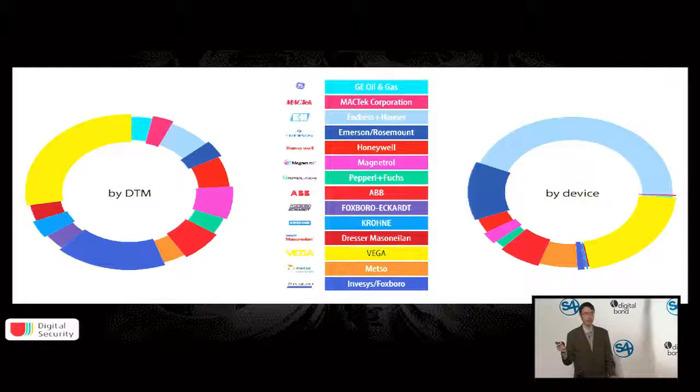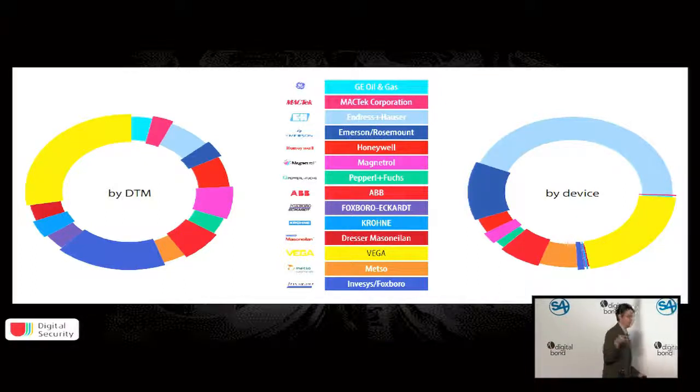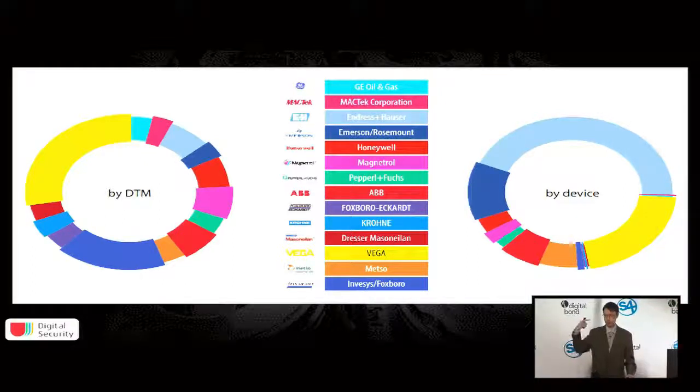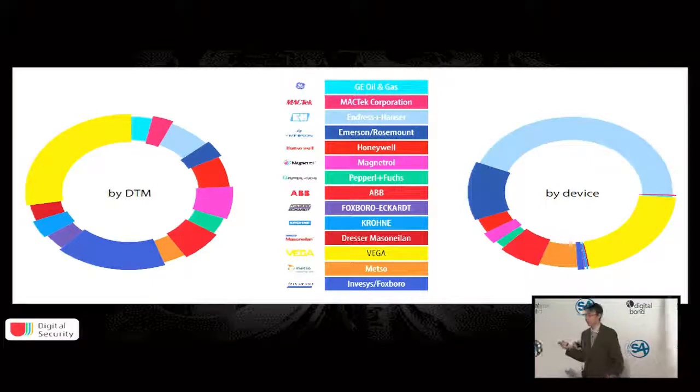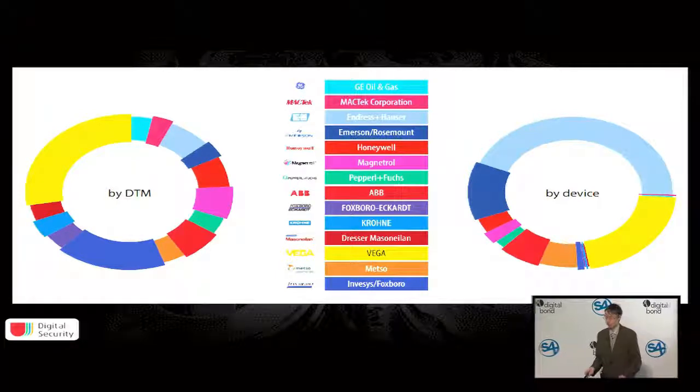So for example, if you have an architecture like HART current loop, then HART to Ethernet gateway, and then the DTM component, you can MITM the Ethernet packet and trigger the same vulnerability as you would, for example, by MITMing the HART current loop. So I think that's bad. They didn't understand the nature of FDT DTM while they developed the components for the FDT DTM.